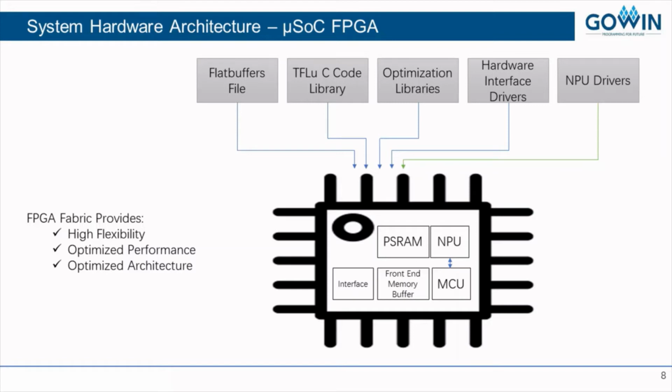So you still have the same kind of setup, but I would say that you have much more flexibility in the NPU because it's soft. And by soft, I mean it's in the FPGA lookup tables. And then in terms of hardware interfaces, you have way more flexibility. So first, you can utilize all of the I/O count on your device. So all of the I/O is highly flexible.